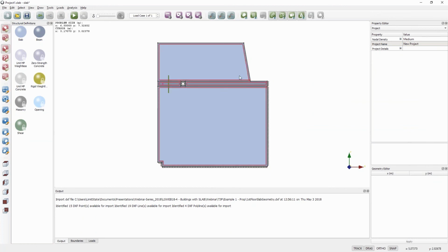We can see the red lines around each of the different zones is representative of the pressure loading. The green line here is the line loading that we've got from some of the props, and the little pink load, if you can see there, is representative of the point loading. So we go through all of this and we specify all our different loading for our particular load cases.